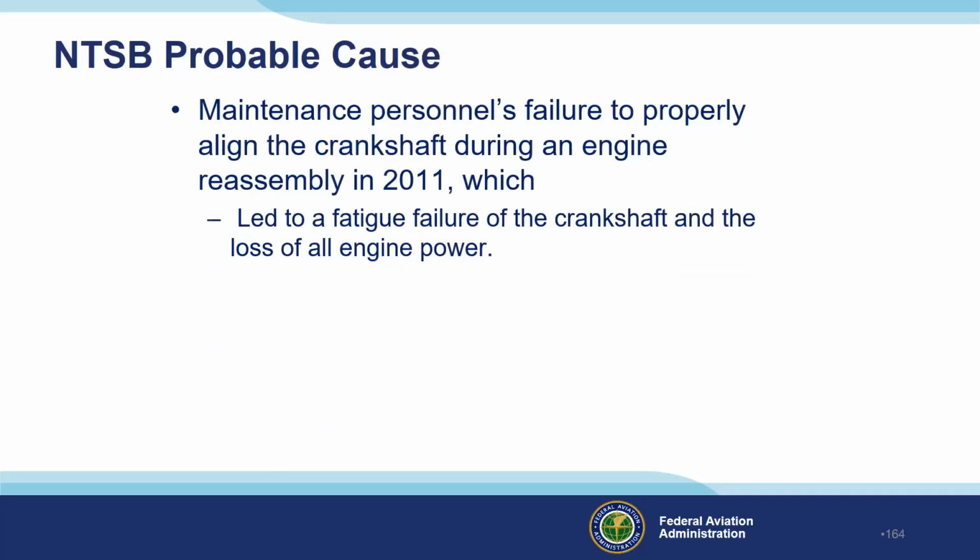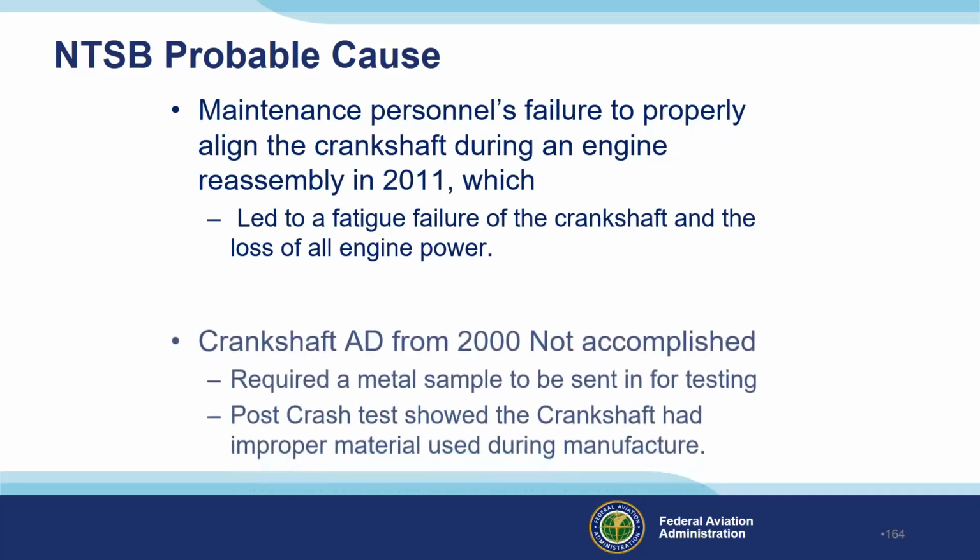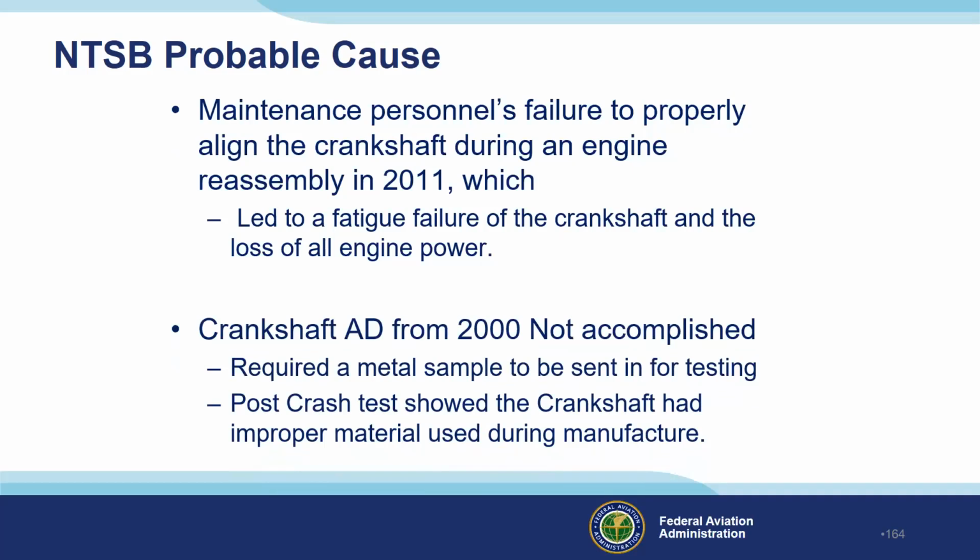Probable cause from the NTSB: maintenance personnel's failure to properly align the crankshaft during an engine reassembly in 2011. This led to fatigue failure of the crankshaft and the loss of all engine power. Now, there was an AD from 2000 that was not accomplished.